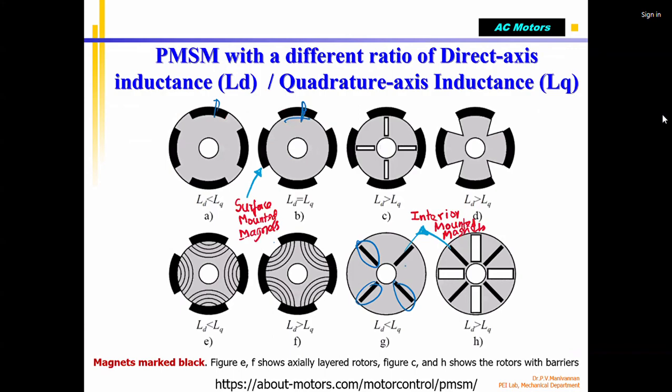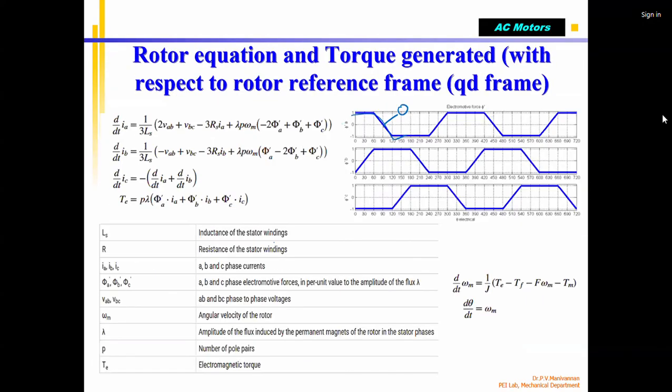But here you have to cut a slot inside the core and insert the magnet. That is a complicated process. So the interior type rotor fabrication is a little complicated compared to the exterior type, and that affects production and manufacturing cost. That's what we are talking about here.